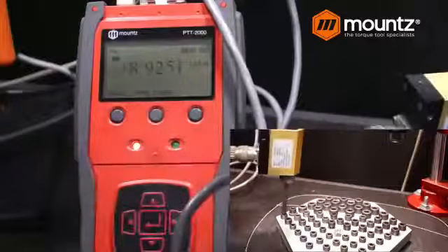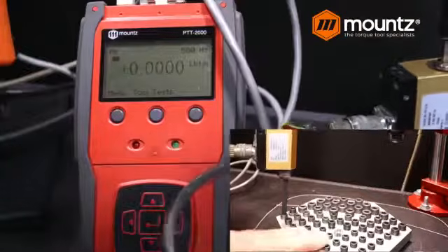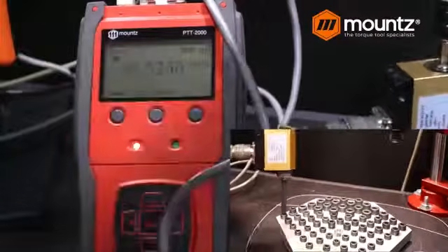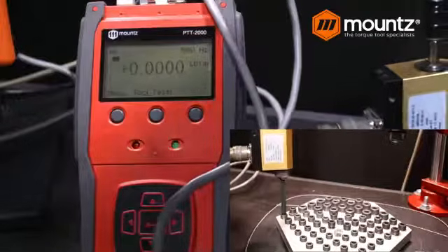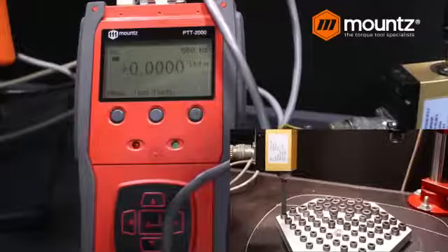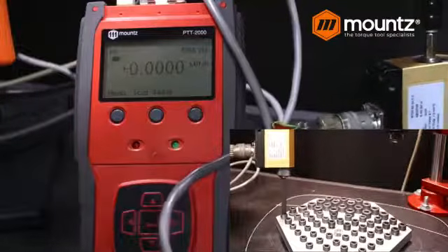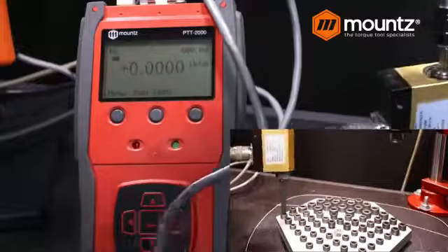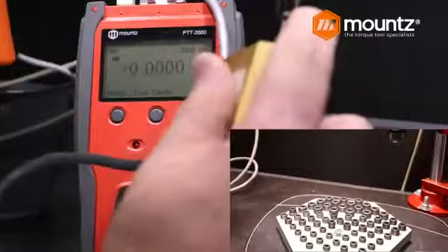And now this is giving us a value at 8.9 inch-pounds or so. If I go ahead and run it again, we're now at 8.5. So this gives us that ability to, again, measure what's happening on the thread block here, which could be representative of an application. So this can be done, again, with a hand tool.